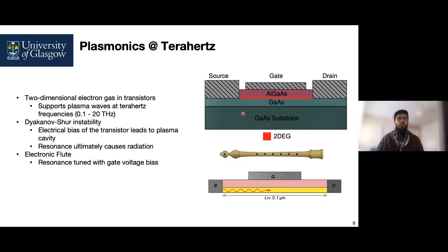It was discovered that upon some unique boundary conditions being met in this field effect transistor, the waves trapped inside this heterostructure tend to radiate. This phenomenon was then called the Dyakonov-Shur instability.